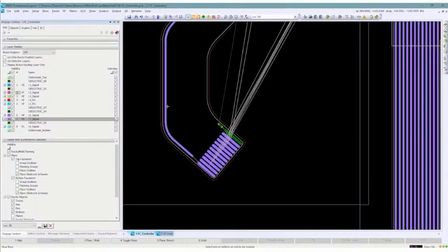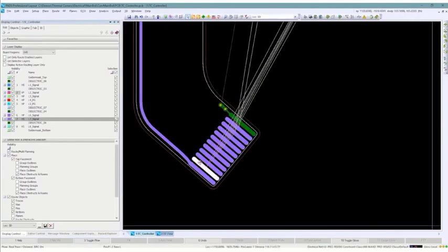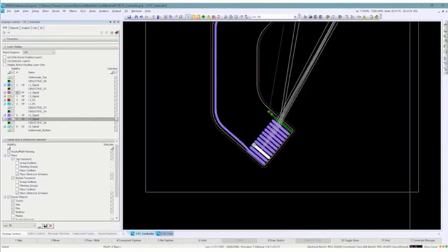the exact contour of the flex edge, eliminating the tedious work of routing the rounded corners we need in flex and trying to follow a complex shape that your flex might be in the first place. And then to finish that trace, we can simply just click the multi-route. All right. And then it's just a repetitive process from there on out doing the rest of them. But now we can use this trace actually as our guide for all these other traces.